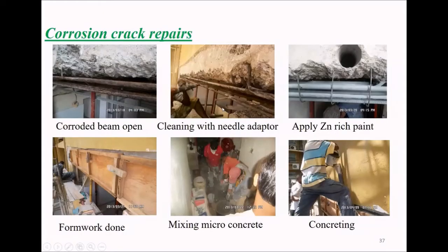And these are some corrosion repairs that we have done. We found corrosion of this reinforcement, and there are no stirrups. All stirrups actually corroded and separated from the main concrete. Right? This is mainly due to this exact location. We found bathrooms, washrooms. This is a commercial building. They had several toilets over there. Due to this water leakage, maybe within 2-3 years, this beam was totally damaged.